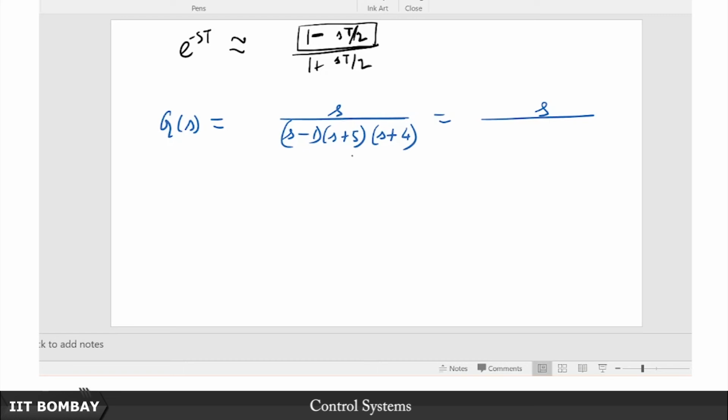Here you can actually see what the poles and zeros are, but typically what you are most likely to encounter is a transfer function given in this form, when you do not really know what the poles are: the denominator s cubed plus 8s squared plus 11s minus 20. This is essentially the same polynomial, by the way. I am just writing it in this form so that the poles are not explicit from the way it has been represented.